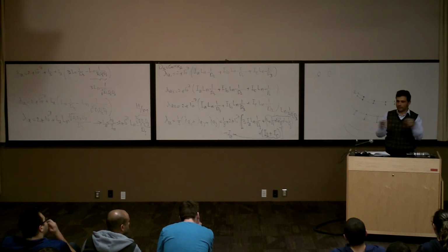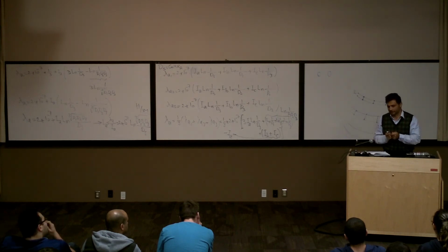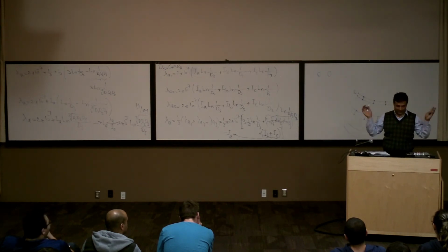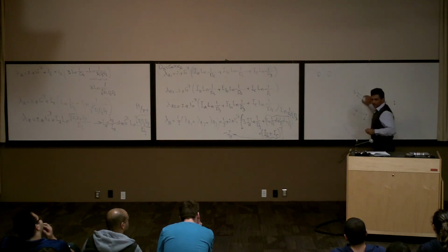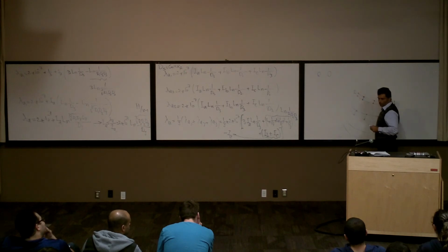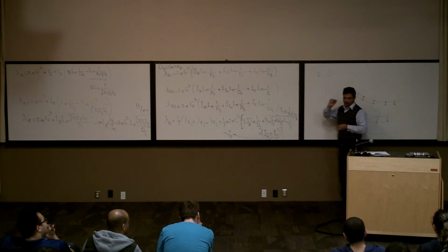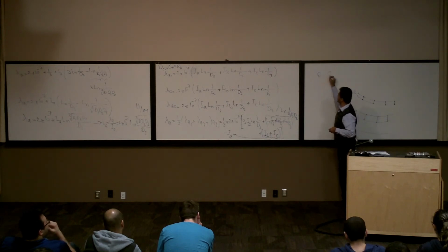They don't want them to go like this and hit each other, because every time they hit each other, even though they have the same voltage, it is still going to cause transients in the system. It's not going to blow anything, but it's going to cause lots of transients. They want to keep them like one conductor. There are three different combinations. It could be two, it could be three. This distance is D. Or they can put it this way.